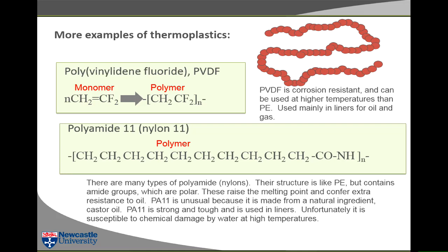And eventually, the thing that limits the lifetime of a well is when it starts producing so much water that it's not worthwhile operating. So oil-produced fluids contain some water. And if you're going to use it with nylon 11, there mustn't be more than 5% of water in it. Otherwise it will start attacking these bonds.